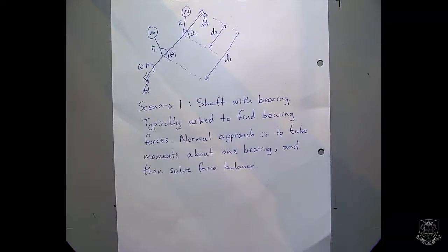so once you've decomposed using the tabulation what's happening in each plane, you can kind of treat this shaft like a beam, if you like, that's having loads applied to it. If you take moments around one of the unknown bearing forces, it means it's out of the moment calculation, isn't it? And then you proceed as you would have done with your other mechanics problems.